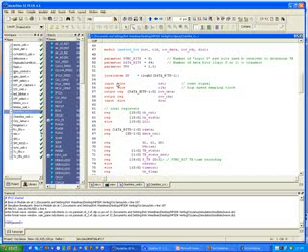And in the Verilog, there's a Verilog 1995 standard, there's a newer 2001 standard, and in the newer standard you're allowed to go ahead and just put the wires or regs right here on the same line as the input and output. Typically before, you would put them separately, you'd just say input like reset, and then you'd have wire reset on a separate line. But you can do that all in one line now. And I'll show you that in the compiler options in the actual Altera tool today, if you remind me if I don't forget.